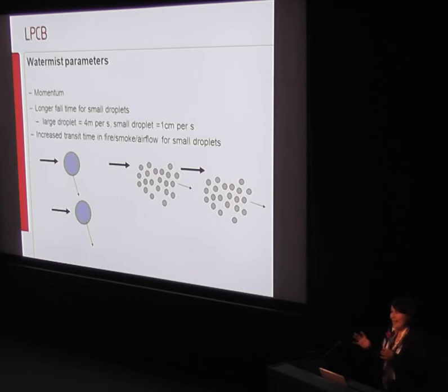Or they can be pushed away, dependent on the fire flow that they're within. And so from a water mist engineer's perspective, they do need to understand these criteria, and hence the attempt is to design methods to ensure you can deliver the water onto the fire so they've got enough momentum, either through high pressure pushing, or sometimes they talk about seeding it with large droplets that creates a dynamic flow that encourages that.